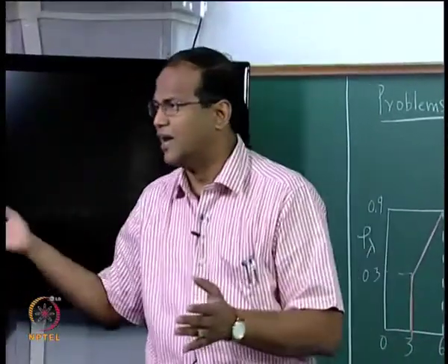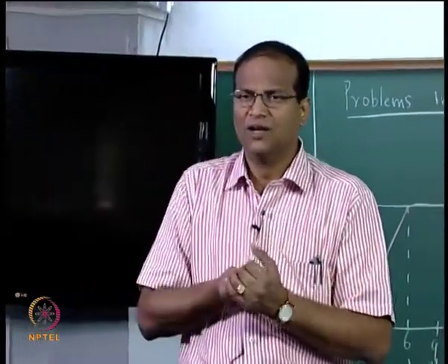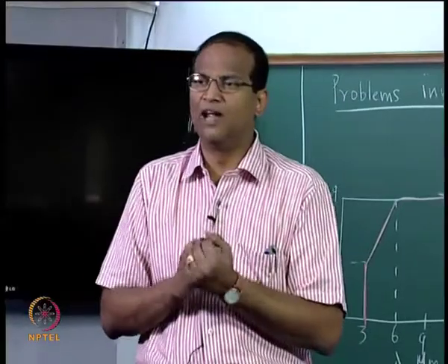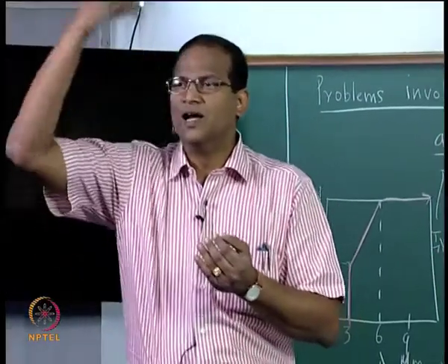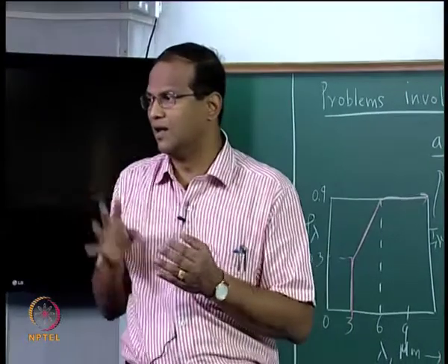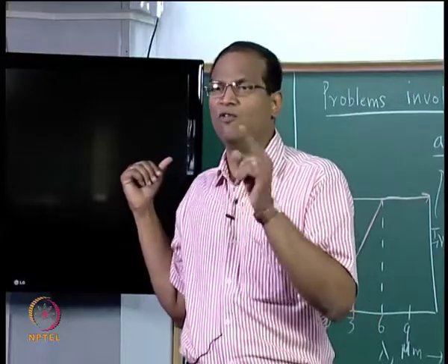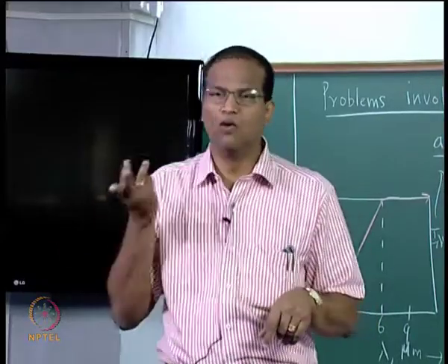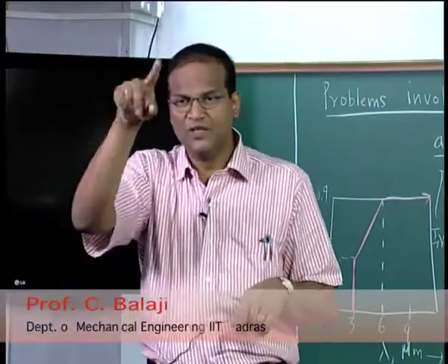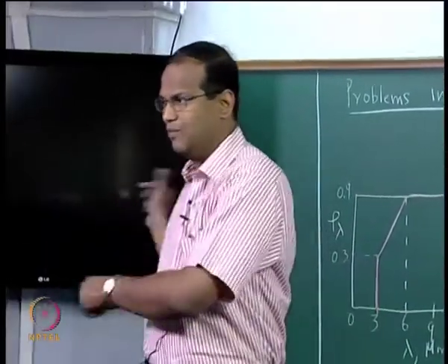I will give you I lambda I, and then I will give you the distribution for alpha lambda and ask you to get the alpha. Or I may say that the irradiation is from the sun, and I will give you epsilon lambda. From epsilon lambda you have to get alpha lambda. Or, in this problem, one more variation is I give rho lambda and say it is opaque, then using the relation 1 minus rho lambda is alpha lambda, you can proceed like that.